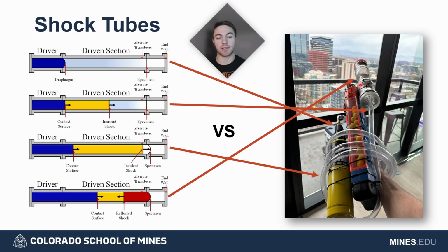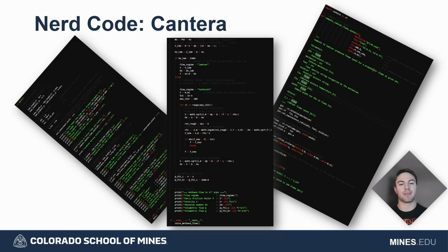And if we had a pressure transducer, we could put that on there and get real-time pressure data for what's going on inside that chamber. And then finally, we have our combustion chamber, and that would be the resonant chamber on the device. This resonant chamber forces the gas to expand rapidly and would generate the shock, hence shock tube. Cool.